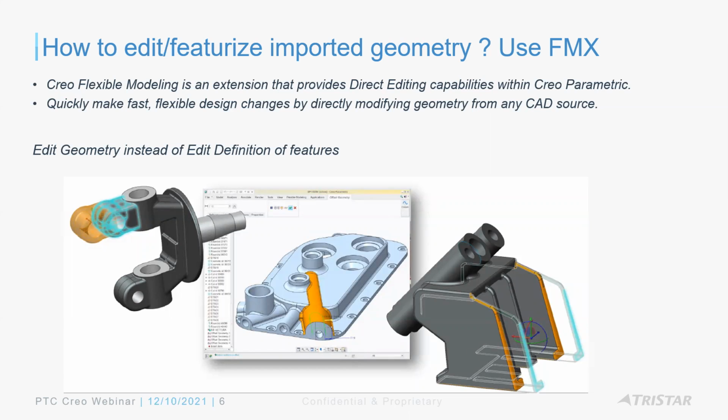Now this is also included in the Creo Design Essentials, wherein you're just looking at the geometry and you're editing the geometry. You're not looking at a feature definition, you're just editing the geometry, right? You're doing some feature recognition, maybe identifying rounds and chamfers, maybe identifying patterns that might be done in a different CAD system, and you're able to make that change inside of Creo, okay?